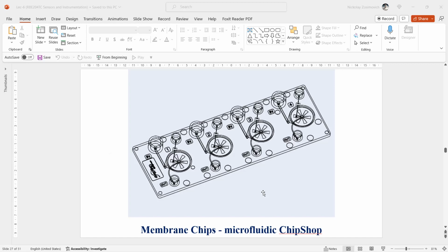Here is a structure without a separate top layer. Both capacitor plates are constructed on the membrane chip using surface micromachining. The gap is realized by selective etching of a so-called sacrificial layer positioned between the two electrode layers. Here too a reference capacitor insensitive to pressure has been integrated. Due to the small dimensions of the structure, on the order of millimeters, the capacitance value is small too, and the change caused by the measurement is even smaller.